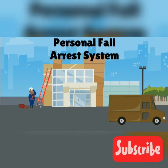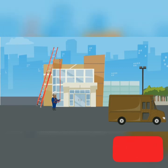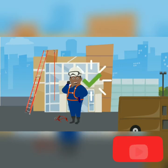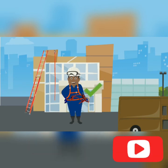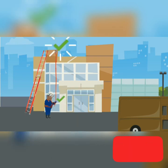One way to prevent falls is to use a personal fall arrest system. It anchors or ties the worker to a fixed object through the use of a safety harness, which is worn by the technician. A lanyard, lifeline, or deceleration device connects the safety harness to an anchor point.